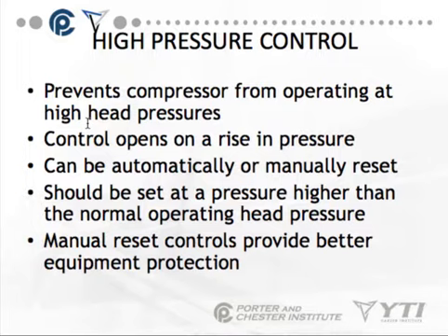The control opens on a rise in pressure. It can be automatically or manually reset. It should be set at a pressure higher than the normal operating head pressure.